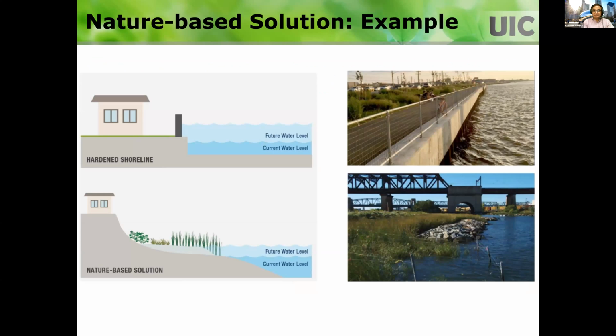But a lot of people are going after these nature-based solutions in the US, and there is a lot of emphasis going on right now. Just an example I want to mention. So this is the seawall. Conventionally, we put this concrete wall. We calculate what is the surge height, and then we decide the height of the wall, and we design it. But the problem is nobody can say for certain that the surge height is going to be that much, because these climate impacts are unpredictable.